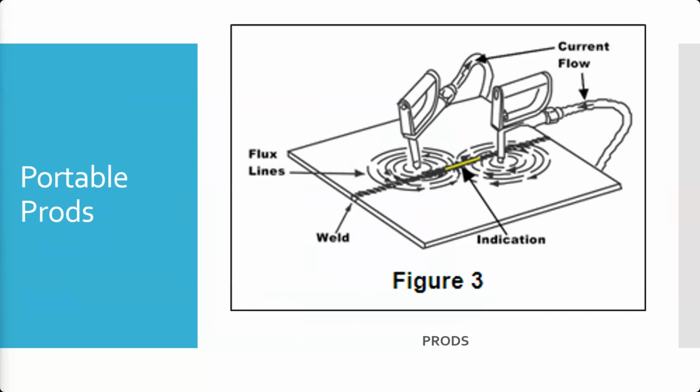Duncan Aviation at their Lincoln facility, they do a lot of third-party contracted NDT and other suppliers like that, where we'd get a bolt that had been in service, it had been tested, it would come back with a new 8130 saying it was airworthy or serviceable to put on the aircraft. So those are our different methods for performing MPI and the different fields that they produce.